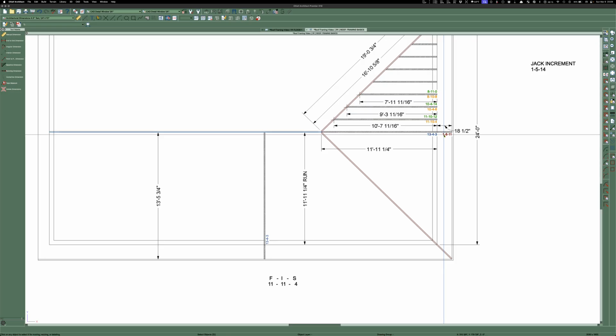But we would keep an 8 and 12. The houses we were doing had very similar overhangs. And so we always did an 8, a 9, a 10, a 12, a 16. And that was pretty much the pitches. And then we had a tail pattern for a 12-inch overhang and a tail pattern for a 16-inch overhang. And we didn't go much beyond 16 down south because we wanted to rip the soffit. They did closed soffit, and so we would rip plywood so we could get 3 pieces that are really close to 16, and we'd cut vent holes in them.